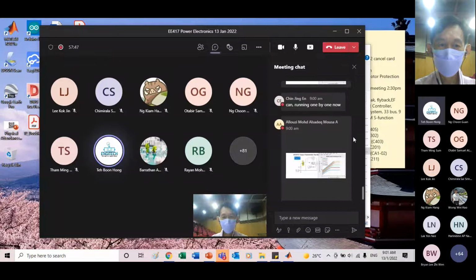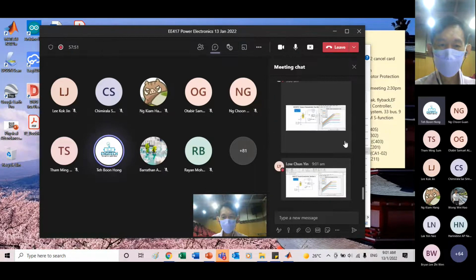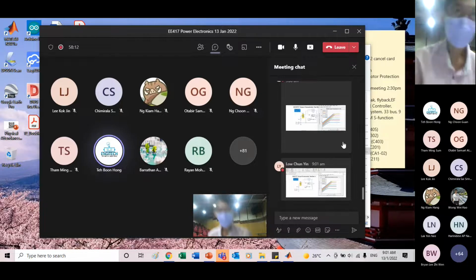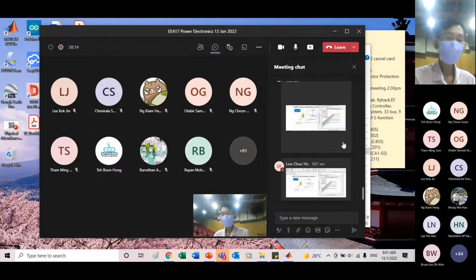So while you are waiting for us, I want to ask a question regarding the transfer characteristic you mentioned just now. That one, the 3.6 for the gate source, because in the sheet I wrote minimum 2 to 4. How did you get the 3.6? Trial and error. Let's say I start with 3, because I take the average between these two.